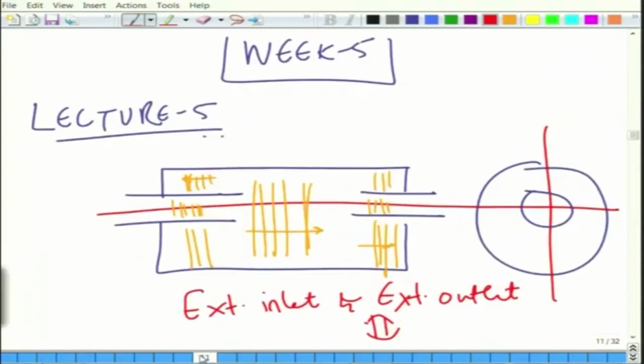And in fact, let me go back to this figure. It is very rarely that we simply use an extended inlet and outlet chamber. We actually connect this by a perforated bridge. Again the same reason, because all situations will have flow, and if you were to just connect the inlet and outlet pipe and not have anything between them, the shear layers will expand and will create a lot of noise. So, that might be counterproductive. So, the flow has to be nicely guided, and the waves can then interact with the annular cavity. Acoustically they will be the same. They can be highly porous.